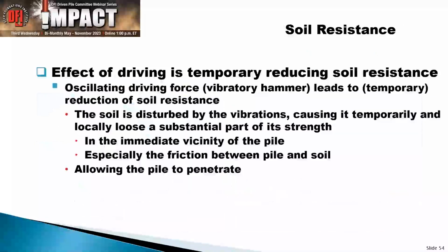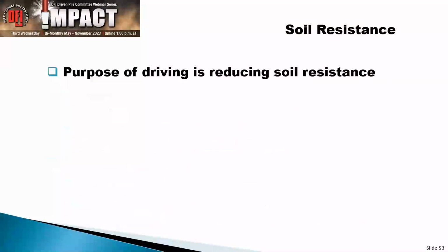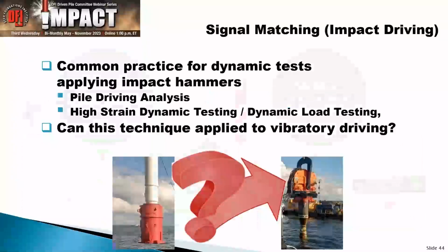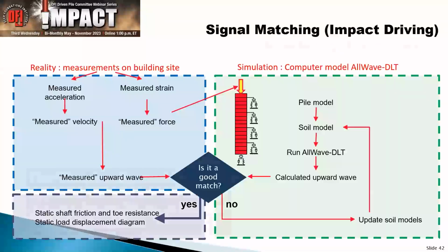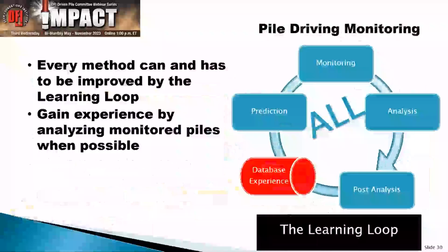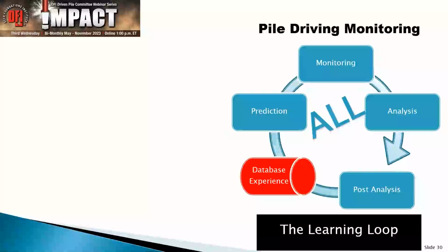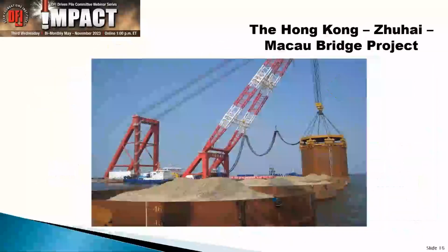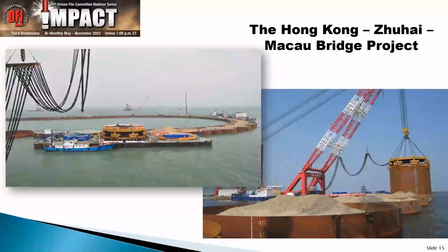If you have a pile like the 82-footer, let me go back to the very beginning, where we had the hammers circled all around the perimeter, and one goes haywire, then we have a problem, because part of the pile doesn't get agitated, it goes out of balance, and the whole thing is a problem.